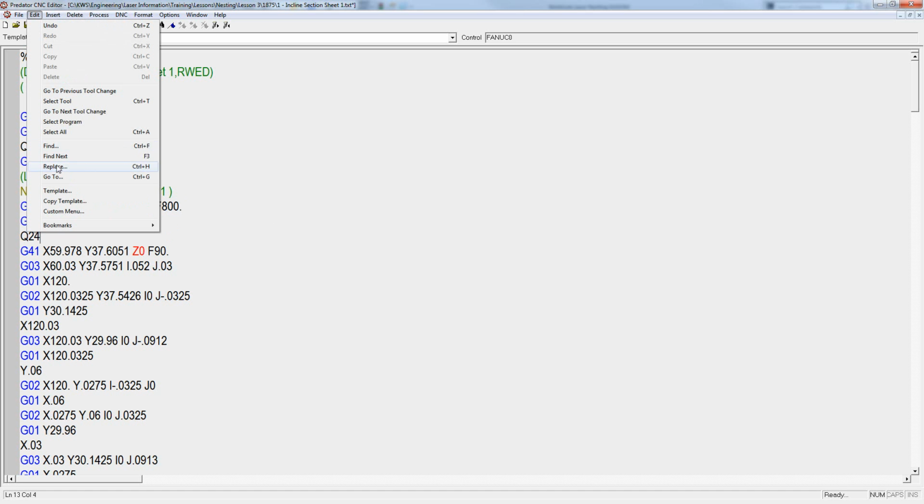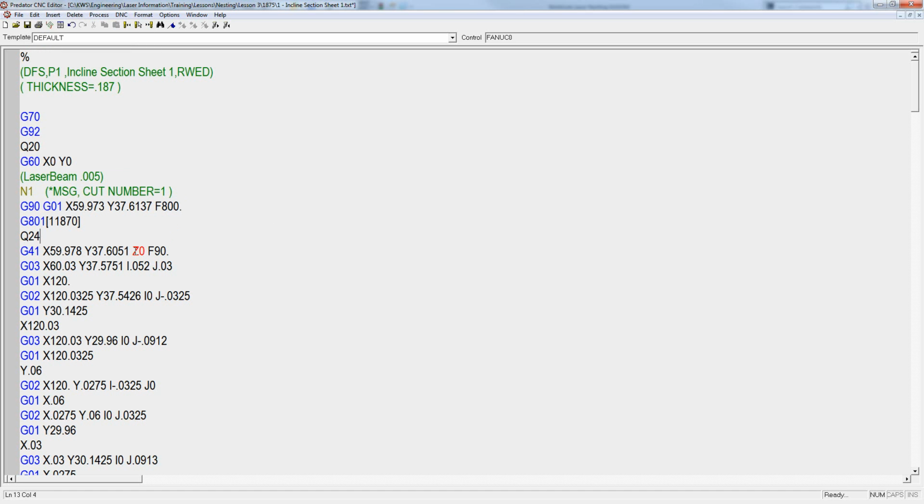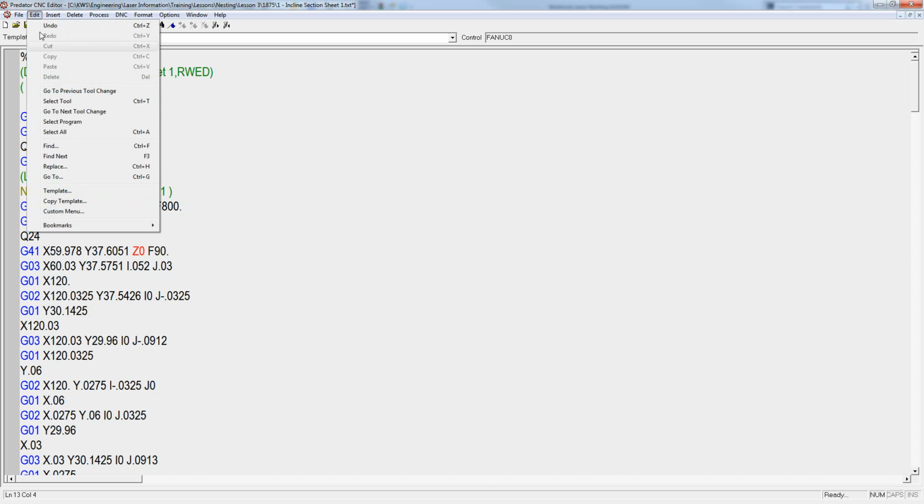And then at this point, we'll go ahead and we'll start getting rid of all the Z values, and we'll start getting rid of all these feed rates. And the reason that we do that is the tech table actually has the feed rate control, the height, the Z, all that stuff is done in there. So we don't really need these here. There are times when we do custom parts where we will need these. That's why they're not removed from our post processor.